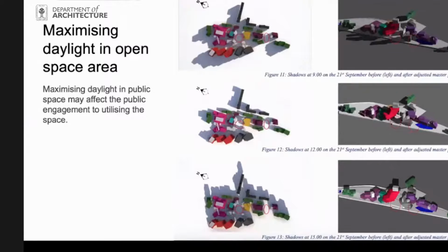You put the public space in the area which gets maximum daylight during the day, or if you prefer more daylight in the morning and less sun penetration in the afternoon, you can apply that, analyzing the surrounding area and urban environment to find the best location for your open space.